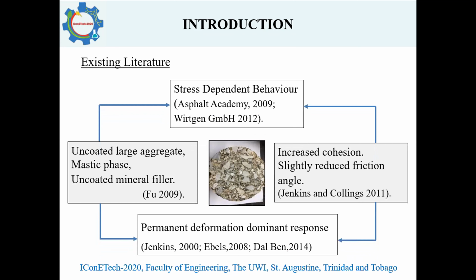It is as a result of these maintained granular characteristics that BSMs are described as displaying stress-dependent behavior, with previous researchers identifying permanent deformation and shear strain accumulation as the dominant response of the material in its long-term life.